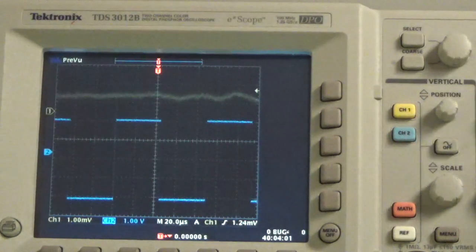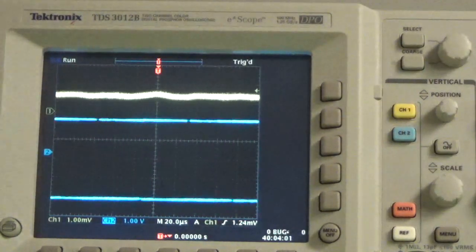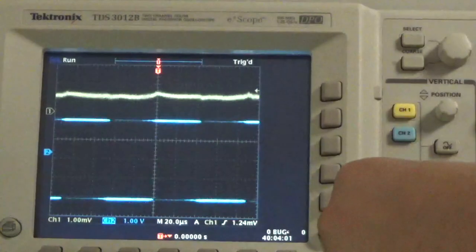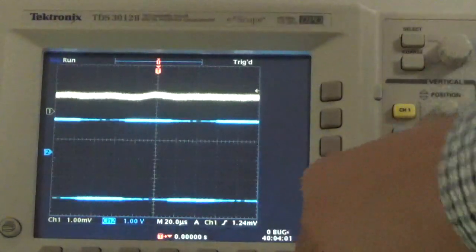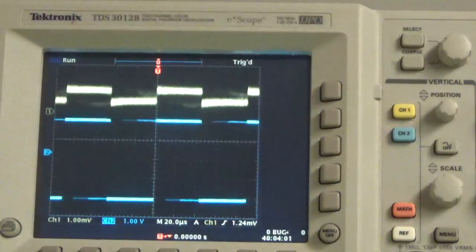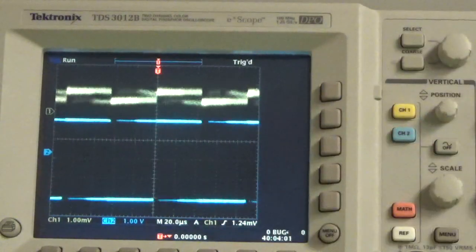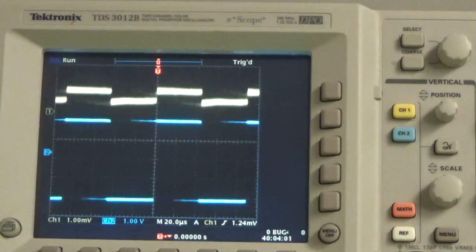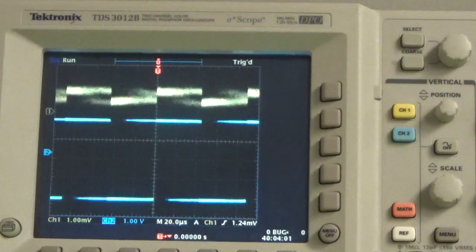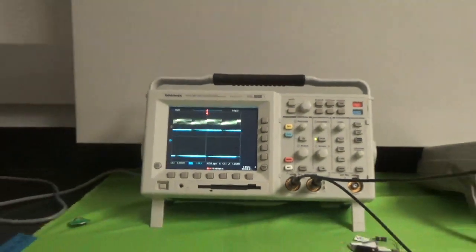So that's great. Now I will try to fix the other coax cable right here. So now we know that the function generator is providing this circuit, the RLC circuit, with 11 kilohertz and V peak to peak 4 volt. So that's great. I will zoom out,